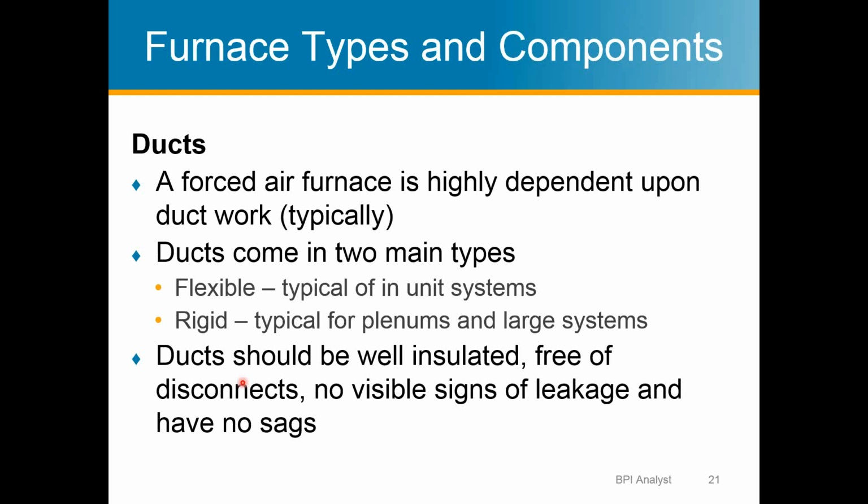So not only do you not want them to leak, but you want them well insulated. And a lot of times you can do a visual inspection and get a good idea. You can also just do a pressure test on the ducts while the blower door is running, and you can get an idea of how leaky they are. But to really know, you need to do a duct leakage test, which is not part of the BPI Building Analyst exam, just a good thing to do on all ducts.